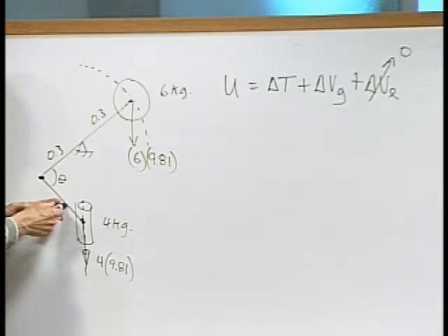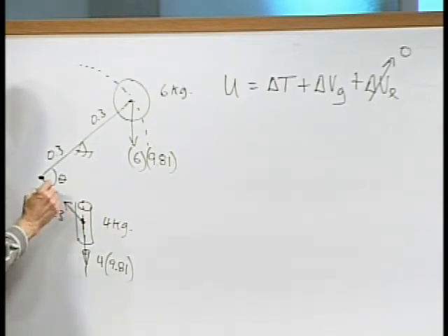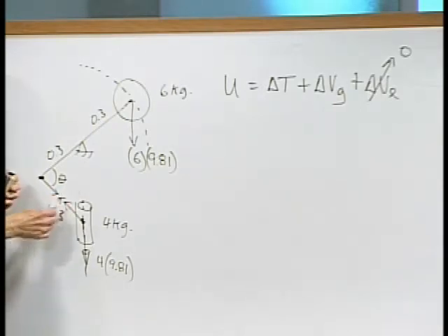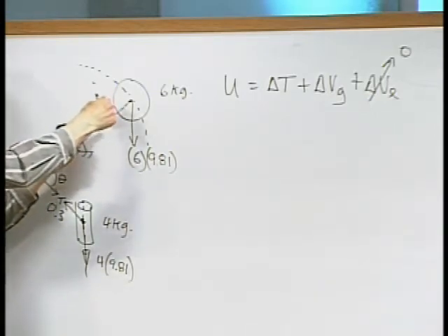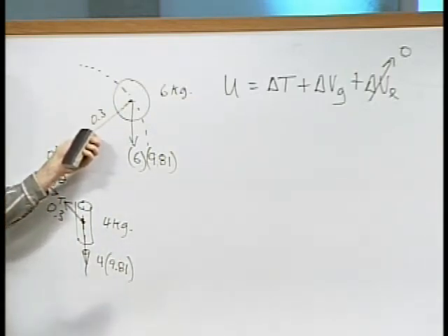Someone was commenting about the fact that if I cut that there, by equilibrium compatibility, there's equal and opposite forces that exist throughout that member all the way through, including the lateral forces that we're not concerned with. The lateral forces that are in there, the bending, the ones that would contribute to shear and bending. Okay. Similarly, in these members, they would be equal and opposing. So we're not going to have to worry about them, to make a long story short.